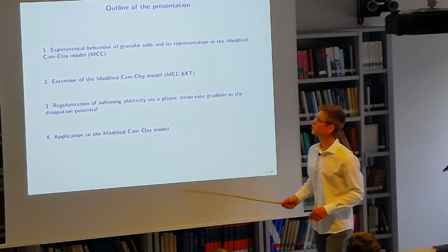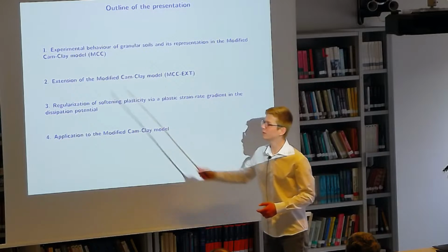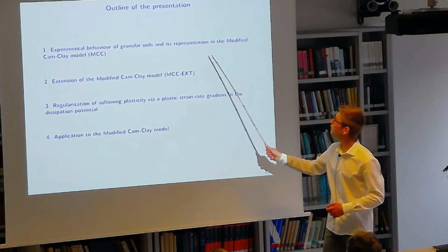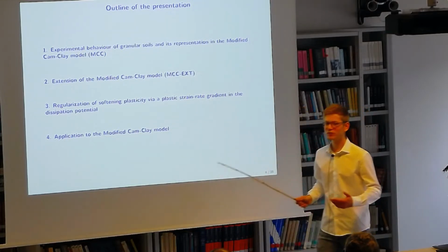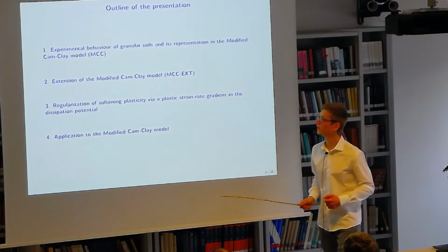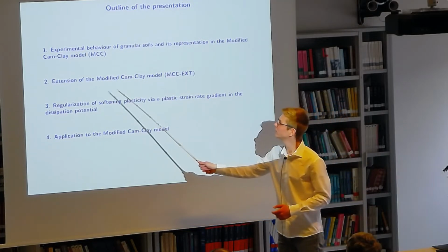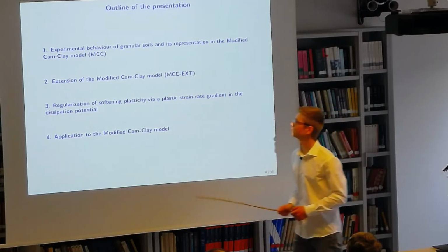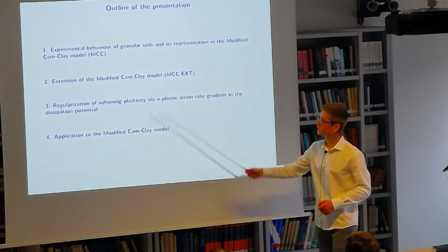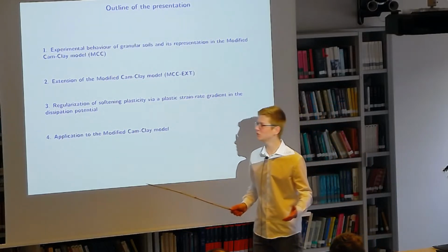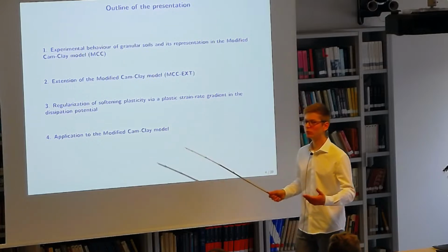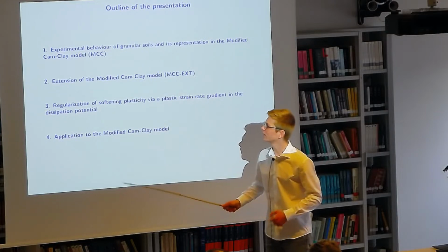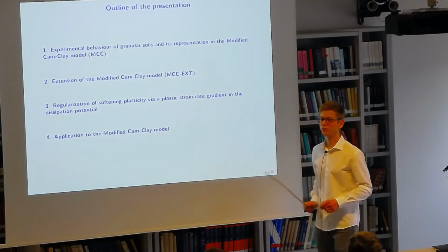The outline of the presentation will be to give some concise experimental elements about the behavior of granular soils in order to introduce a phenomenological model named the modified Cam-Clay, which was taken as a starting point in order to design a new one. Indeed, in order to improve its predictive capabilities, I'm going to propose an extension of this model. The second part of the presentation will be more dedicated to the question of regularization, in which we are going to introduce the gradient of the cumulative plastic strain in the dissipation potential of the model. At the end, this approach will be applied to the modified Cam-Clay.